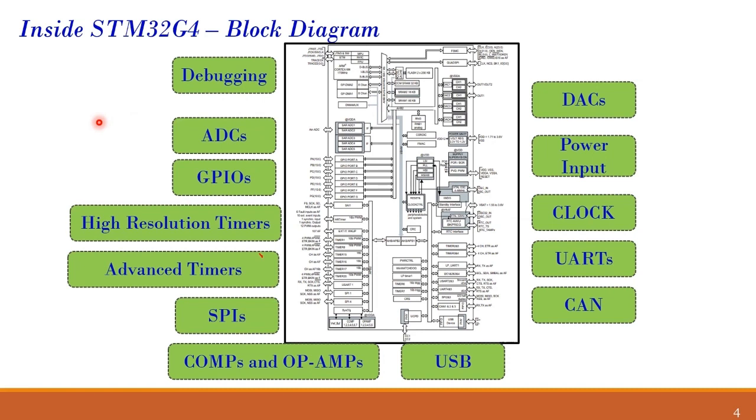The ADC requires a clock coming from the FPGA to trigger it, and the ADC's output has to be sent to the FPGA. So those complications are there. They are external. The FPGA is also a very large block and takes up a lot of space, and in addition you have the external ADC driver stuff. But the advantage with the microcontroller is that you have the ADC internal.